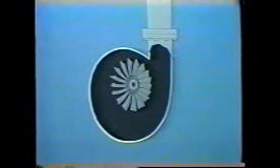For now, to clearly see what happens to the vapor as it flows through, we won't have the impeller spinning. Let's trace the path of the vapor through the impeller. We'll show the path of the vapor step by step. As the impeller spins, the vapor travels along the blades from the center outward. As the velocity or speed increases, the kinetic energy of the vapor increases. The vapor is thrown off the blades by centrifugal force and is then forced against the casing.